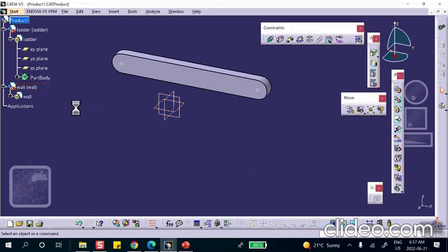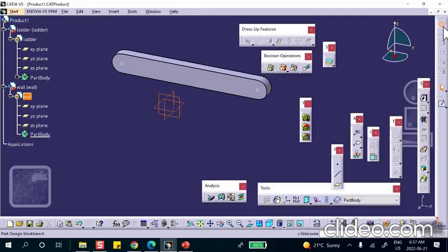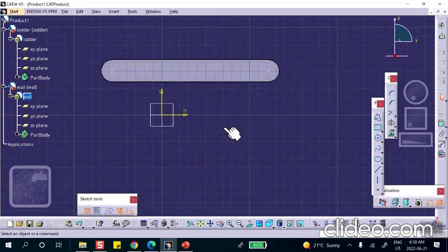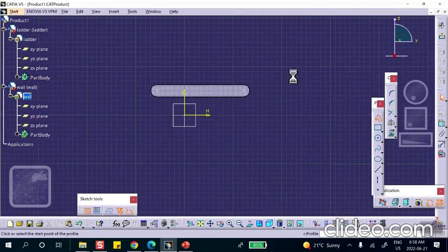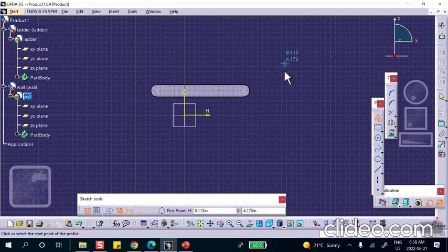All right. So let's double click on the wall. We're going to go into part design. I'm going to be making the wall. So on this vertical plane, I will sketch something that looks like the L that you have, making the wall. So perhaps something like that.